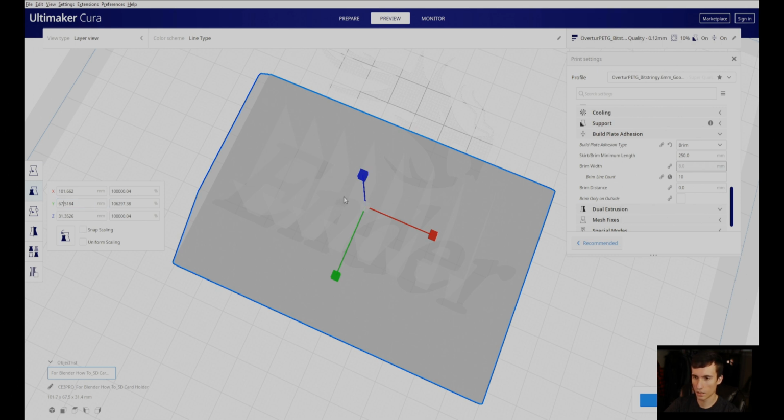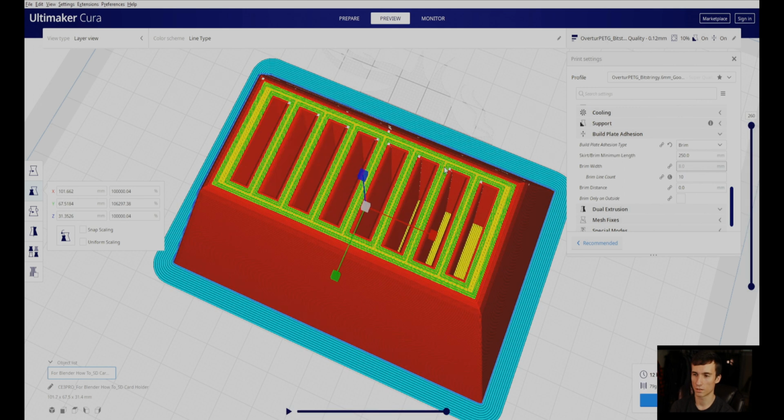And it won't be actually 2 millimeters because it scaled the whole object. So these outer edges will have moved by 2 millimeters, but the inner edges, maybe half of that, because that's the way scaling works. So I'm just going to save the G code, put it on the SD card, delete the old G code.